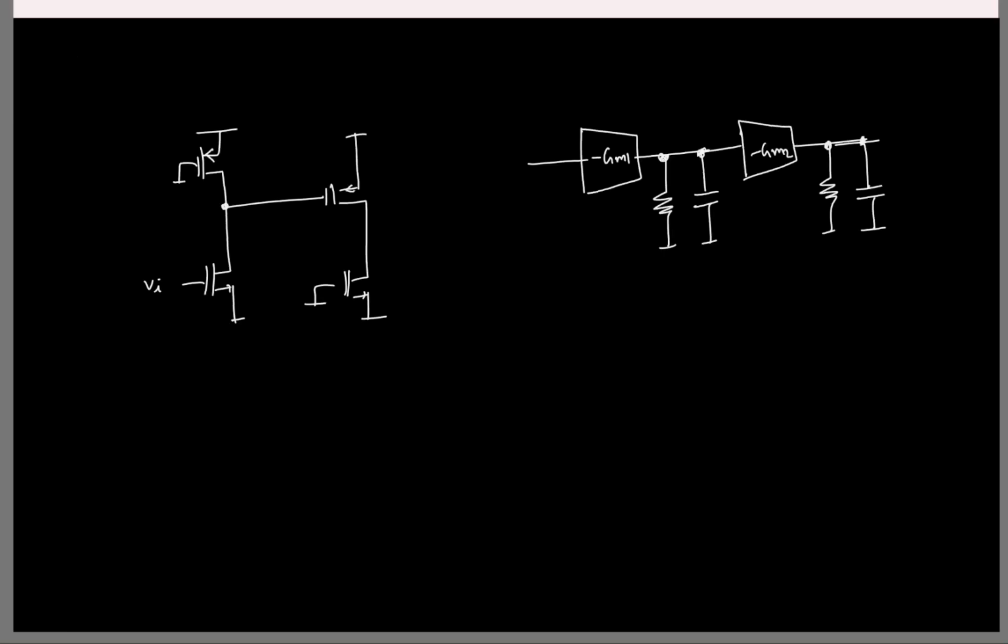I mean, let's say I take this and put it up, forget about the common mode. In the differential mode, is it fine, or do we have to do something? I have a two-stage op-amp. So if I directly connect two stages, will things be fine, or do we have to do something? Yeah, we have to do some compensation, right? Because as such the phase margin might not be good. So what can we do for compensation?